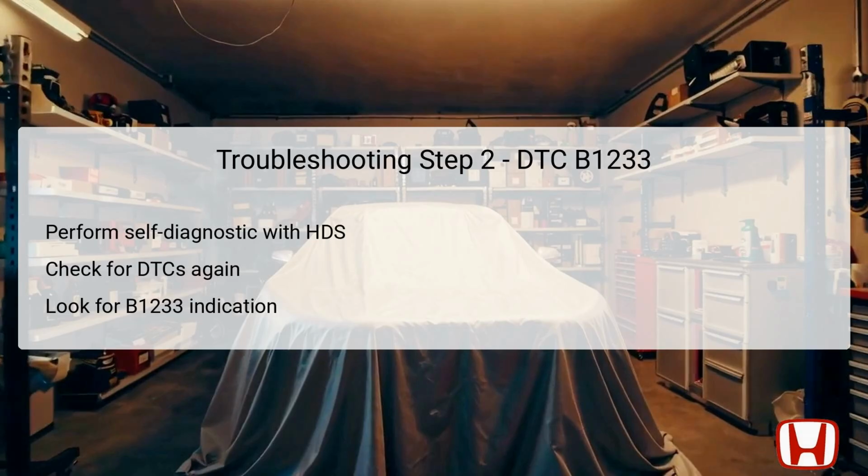If the same DTC reappears after clearing, it indicates a persistent issue requiring further investigation. Conversely, if no DTCs are indicated, it could suggest an intermittent failure, often linked to loose connections or wiring issues.